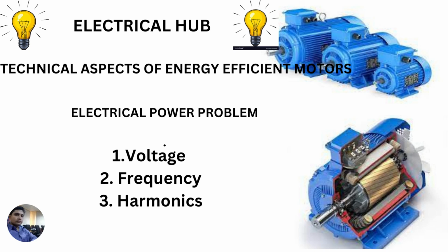Voltage. Due to the unbalance in the voltage, there will be an increase in the operating temperature of the motor.